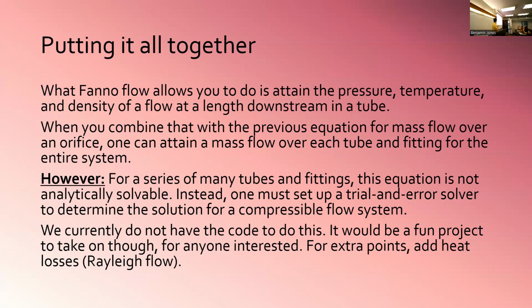However, this equation is not analytically solvable. Unlike the previous compressible or incompressible flow equations, which are solved using the fluids library, this problem is not analytically solvable. For that reason, you have to use a trial and error solver in order to get the mass flow of a compressible flow system.